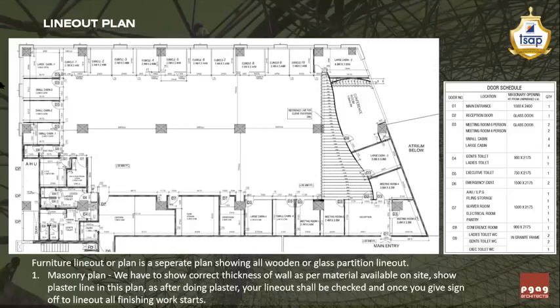So after the complete execution of the flooring of your site, the flooring inside the reception area and the entire site should get aligned with that same level. So you are going to write the final finished floor level as 0.0 mm, and it is the contractor's responsibility to match this level with the RCC slab level. Sometimes the RCC slab level is in undulation.